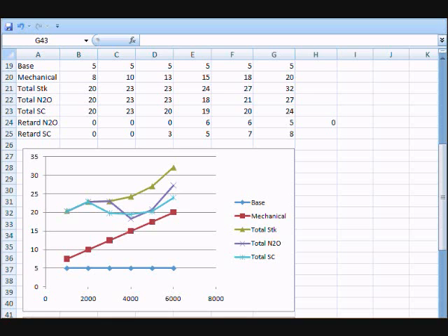Alright, so what's interesting here about these curves is that if you look at these different curves, peak volumetric efficiency and minimum timing occurs at different locations for the three different setups. I mean, the factory car, peak VE is probably around 4,000 RPMs. You can see how this dips compared to this graph.